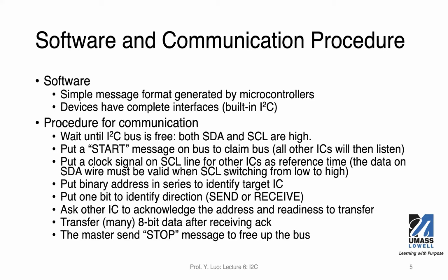It will then put a clock signal on the SCL line for others as a time reference. Because it's a bus, this SCL line can be seen by all the other ICs, which are now listening. And the data on the SDA wire must be valid when SCL switches from low to high. We'll see some illustrations and I'll explain further.